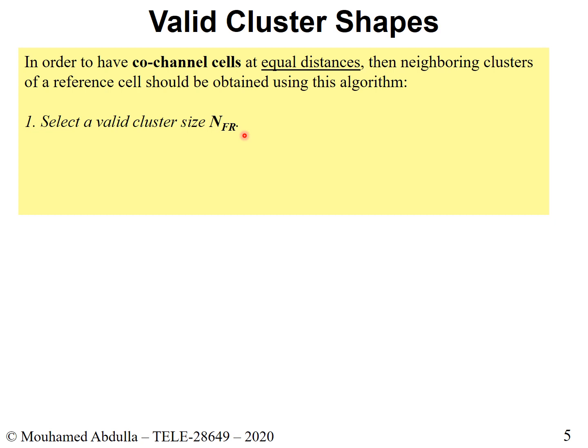There are some techniques right now. You might find some peer-reviewed scientific papers that suggest different methods with beamforming and others where you could in fact increase the frequency reuse from the typical 1 to greater numbers. So there are some techniques that are proposed in different places, but in general, 1 is traditional. That's what we have right now with LTE. So okay, you select a valid cluster size, and we know the feasible set.